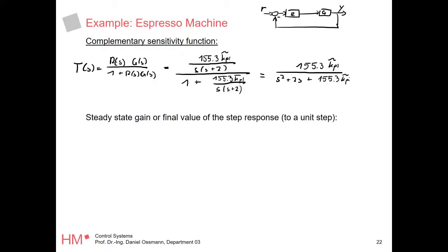That's it. Okay, next thing. If you remember our lab exercise, most of you wrote to me, okay, we are not getting the temperature we actually require. We are not getting to 96 degrees. Yes, a proportional controller is never able to do that for a proportional system, but we've learned an integral controller is able to do that. So let's check what happens now for a step input, right?